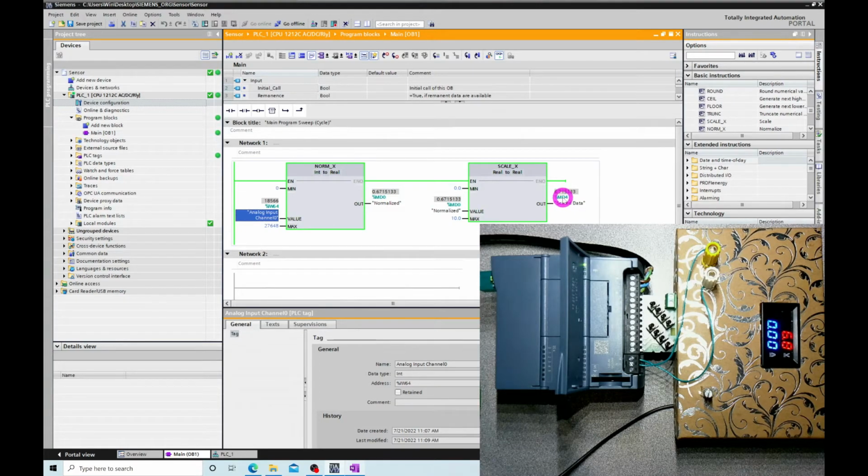Again, remember, you shouldn't put MD1, MD2, MD3, because this is 32-bit. You save in the MD0, so the next one should be 32-bit on the other side. That means you avoid a conflict of the addressing and losing the data that you already keep inside %MD0. That's the reason I put MD4: MD0 takes 32 bits, so MD4 starts after that, so there is no conflict of the addressing. Again, if you don't understand this, watch our previous video, internal addressing in PLC.